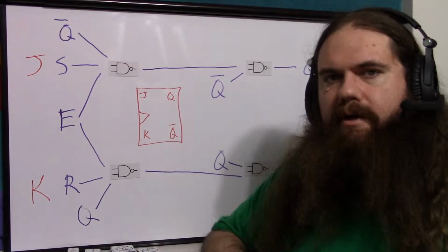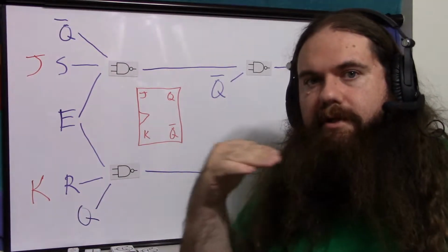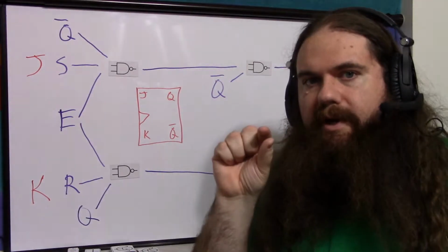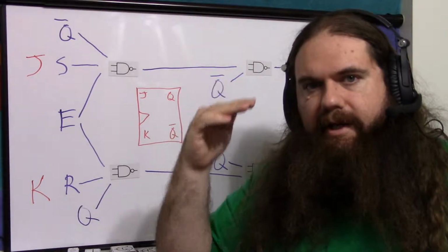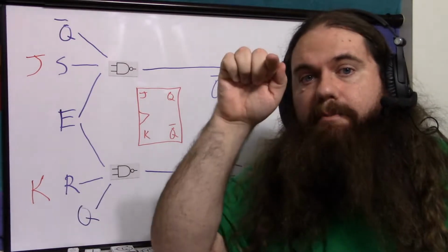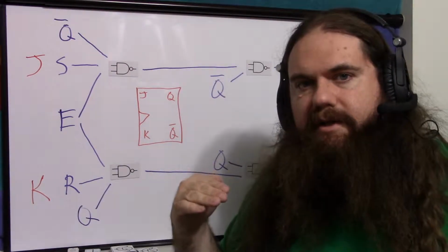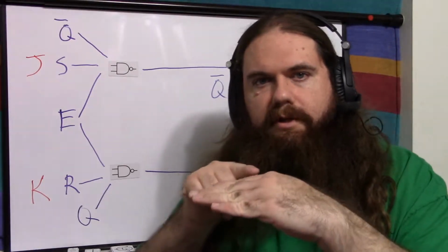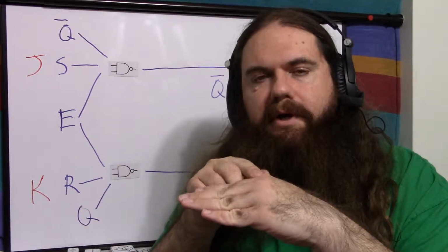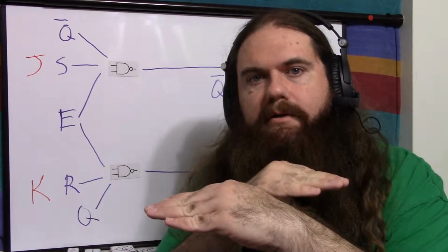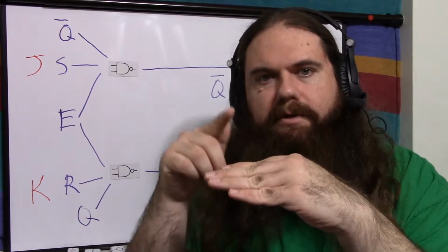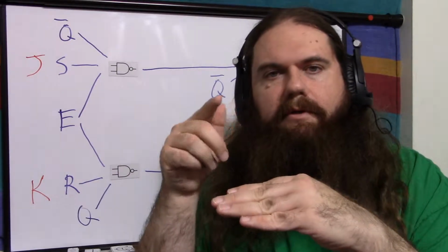That means when the clock will normally be low, when the clock goes high, it'll go high very briefly and then go back down. That's called rising edge triggering. When the clock goes up, it'll very quickly go back down and it'll sit down. So there's 4 different edge triggerings. You can have a clock that's usually low and it pulses high when the base clock goes high. It can pulse high when the base clock goes low, or it can pulse low when the clock goes high, pulse low when the clock goes low.